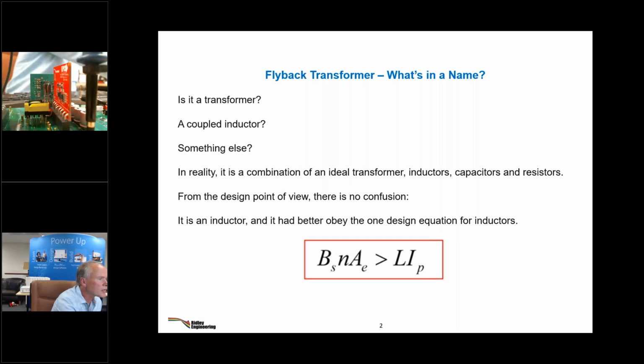Possible reasons for the hissing noise in the transformer. I think I covered that because our circuit had a little bit of hiss. When you see that jitter, you've got to go probe the waveforms, and you're going to see jitter somewhere. Hissing is the sound of chaos in your converter. When it goes into a chaotic operation, that's when it's going to hiss at you. So you're switching at 200 kilohertz, but that will create low frequency harmonics that you hear, and they're going to be sporadic and all over the place. That's why you hear hiss. Hiss means white noise, and white noise means you've got lots of frequency components in it. It's very common in a flyback.